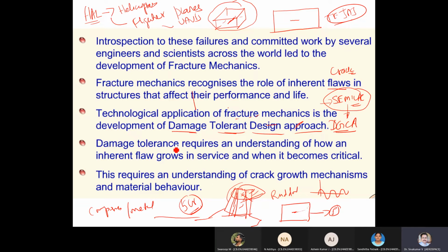So the damage tolerance approach requires understanding how an inherent flaw grows, from one point how it is growing in service. This is service load. What is service load? Let us say a flight, a rudder with a small crack, and I'm just allowing it. Every day in the morning, the pilots take the fighter, go for a round and come back. Isn't it a practice training every day? One day half an hour, second day half an hour. So the load goes up and down.